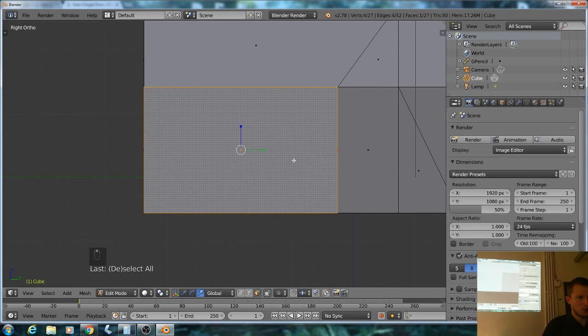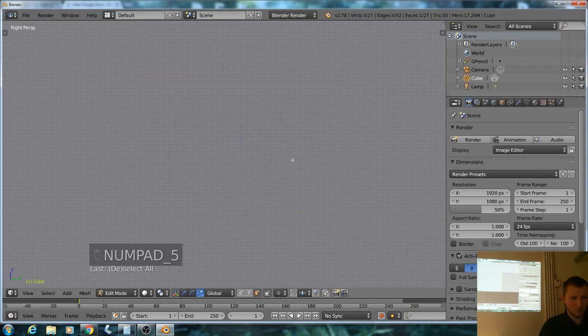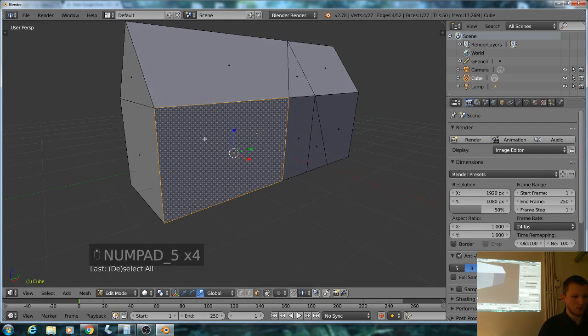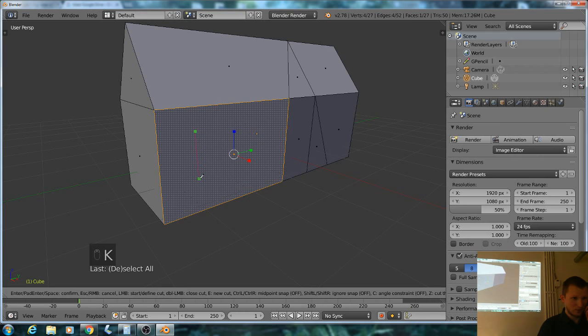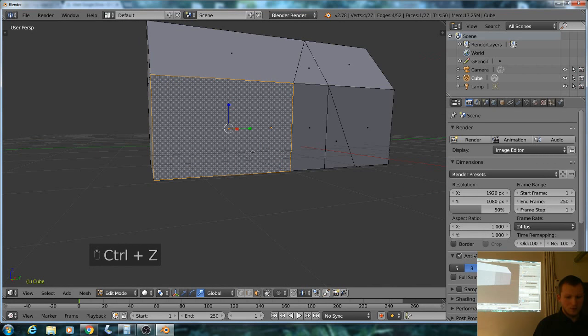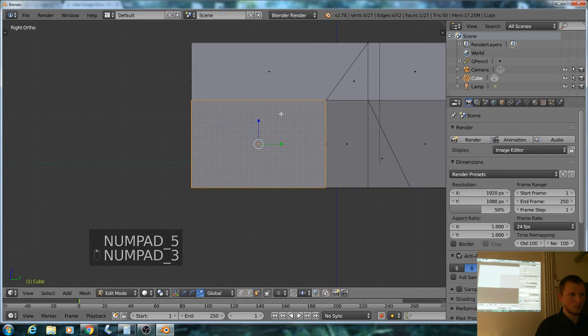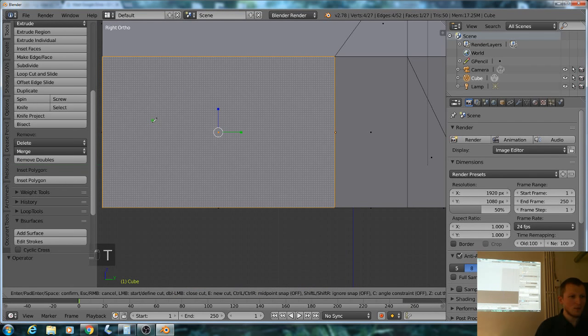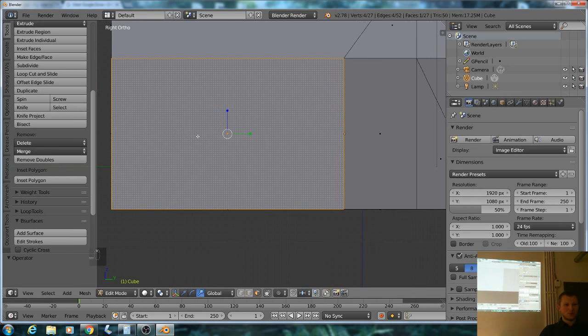And currently it's probably a good idea to switch off the perspective, because if you try to draw something with a knife tool from a perspective view that's not in line with the axis, it's really difficult to make it straight. So, orthographic view from the side, I use the knife tool, and still it's pretty difficult. How do I know it's exactly 90 degrees?